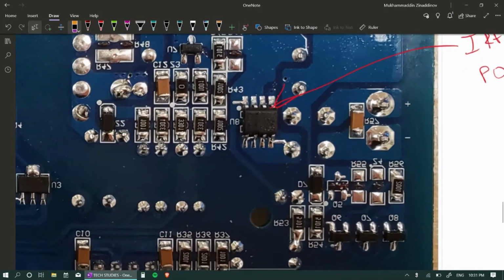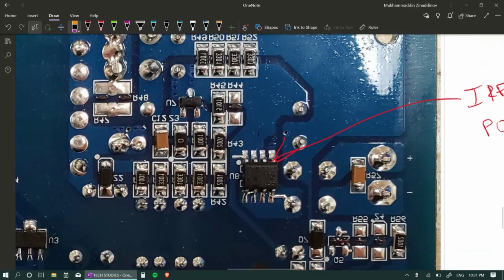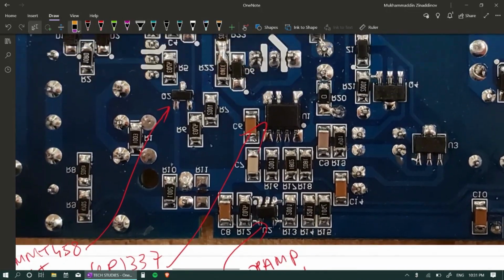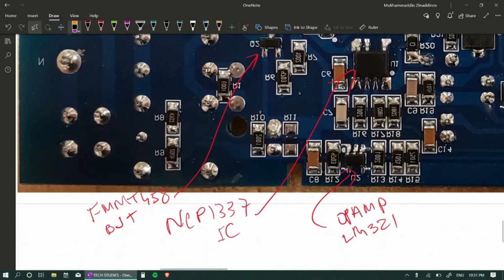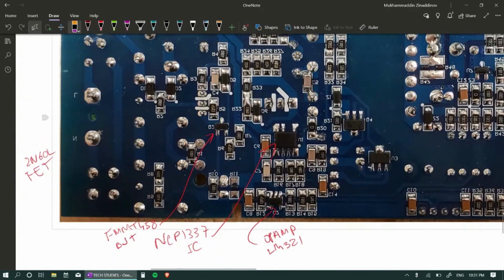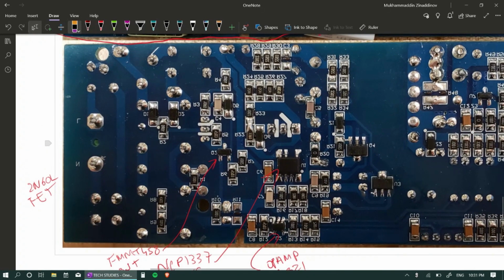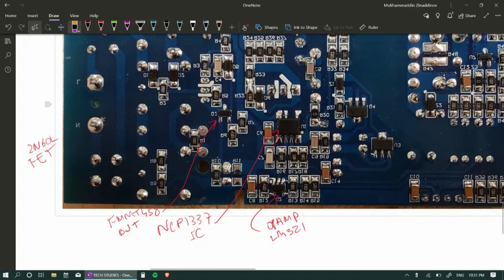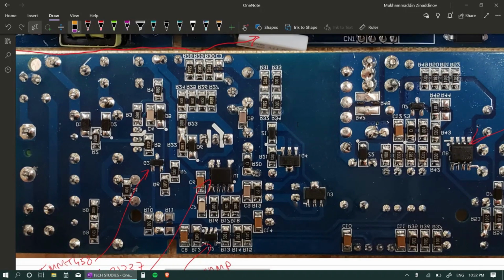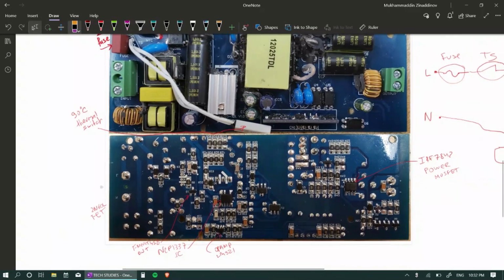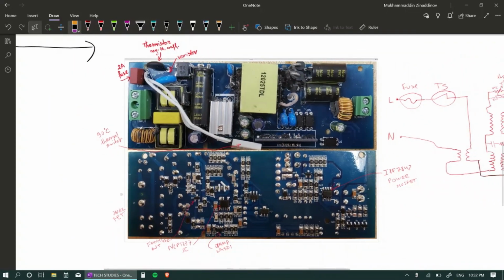Approach number 2 is to look at the ICs and look up their data sheets and application notes and the recommended circuits that are provided there. Basically, the logic behind approach number 2 is, again, due to the fact that the LED drivers are quite ubiquitous circuits, and these power converters are also quite common.